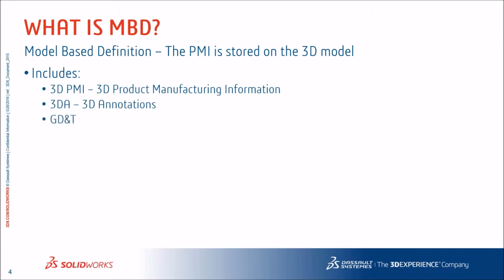So let's start by defining MBD. It stands for Model-Based Definition. It's storing all of the manufacturing information in the model itself, rather than in a drawing. You may have heard the acronyms like PMI, Product Manufacturing Information, or 3DA, 3D annotations, commonly used in the automotive industry, and so forth.